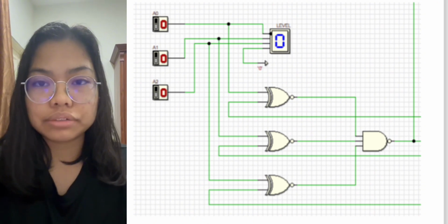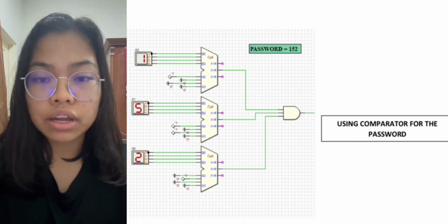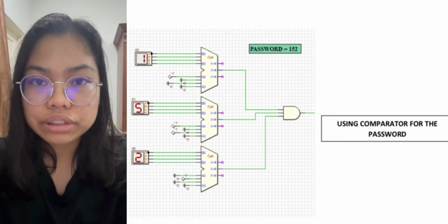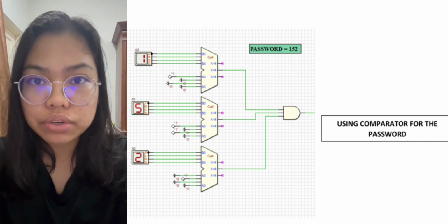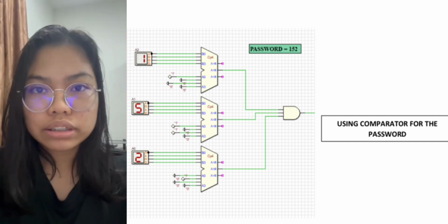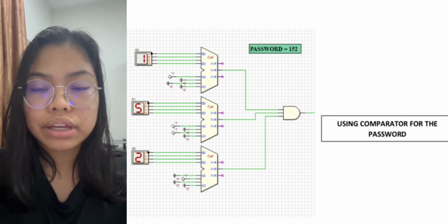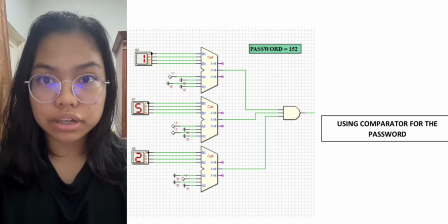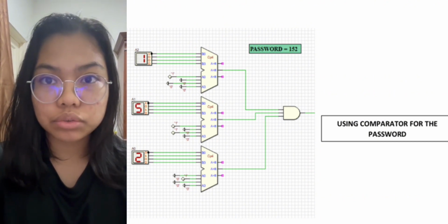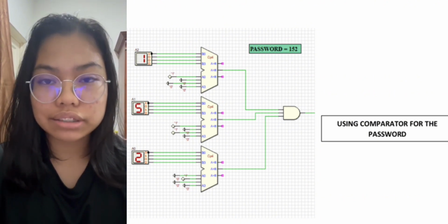close or open. As for the advanced feature, we have a password. When using a lift, a password is required for the security system. Since the password has 3 digits, we use 2 comparators in the circuit. Each comparator's output will be connected to input X, power, and start.